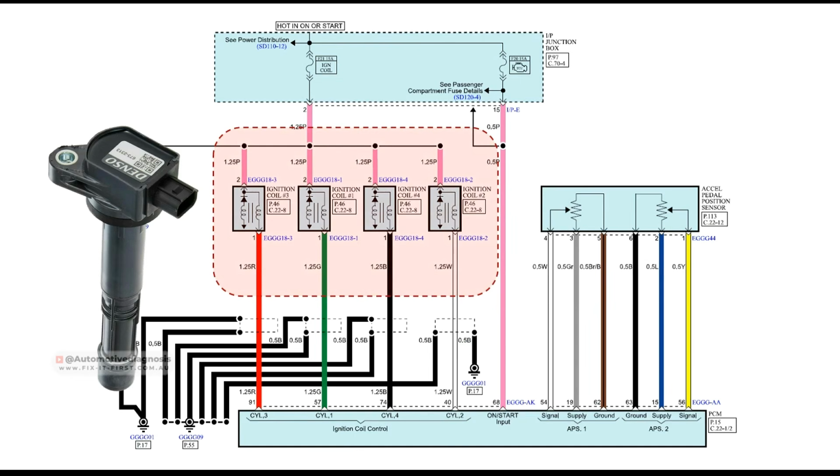On the next page, we have the ignition coils. Of course, you may have different type of ignition coils. You may have wasted spark. You may have coil-on plugs with 2 wires, 3 wires, or 4 wires. We have different videos for all of them in our channels, so you can find the videos in the video description as well. In this one, we have coil-on plug with 2 wires.